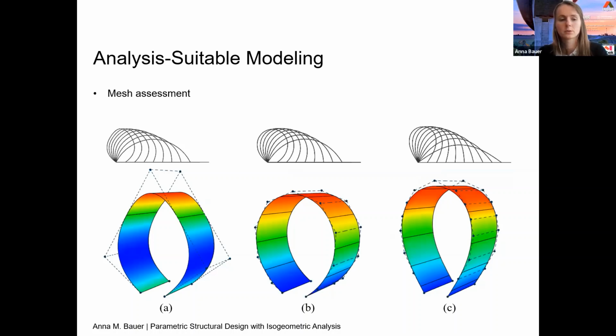So if we only use a few control points, just as for classical finite element analysis, the result is not really good. Here I tested the elastic curve, where we bend a simple beam or a shell strip. It's possible to depict the flat surface with only a few control points, even 4 would be enough. Here I tested 10 in order to be able to even bend it. This is also one thing in isogeometric analysis: as you can depict smooth shapes with only a few control points, it's easy to forget that you need to add some degrees of freedom in order to make it possible to deform the shape into the necessary equilibrium state.